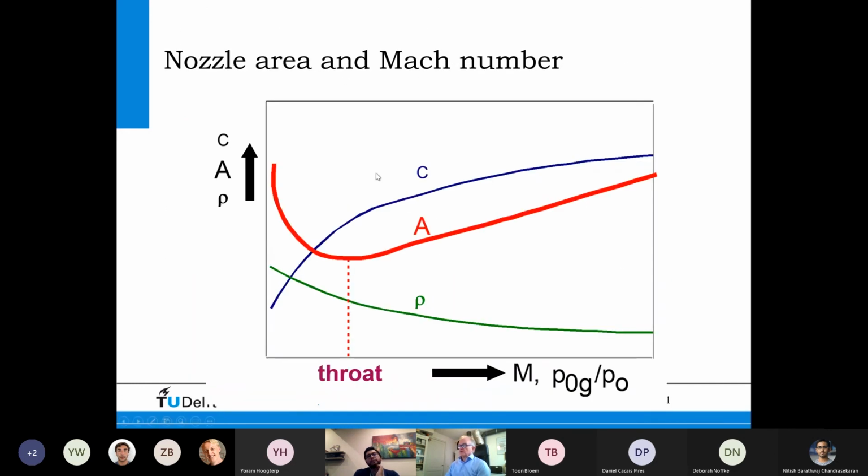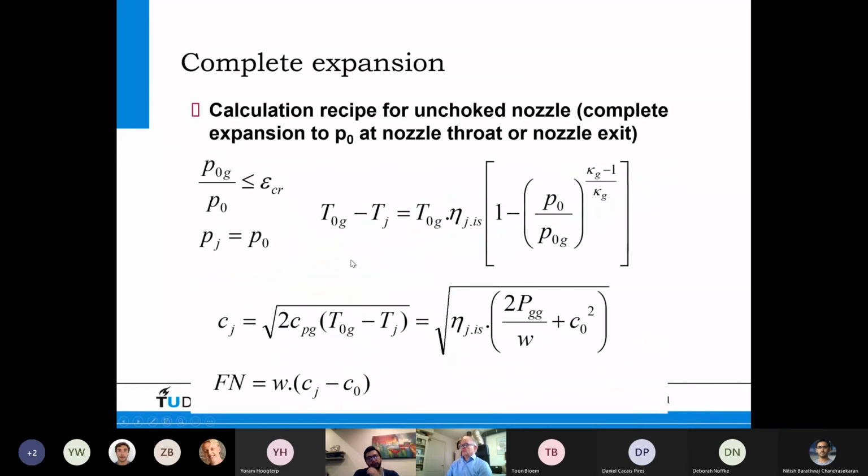So you could say that, well, this is of course a very weird shape, but this convergent trend here is what is used in a civil turbofan engine, but then an F-16 engine, for example, would do this, and then also there would be a structure in this sort of shape with a divergent end, and that end is then also variable, and also the throat area is variable.